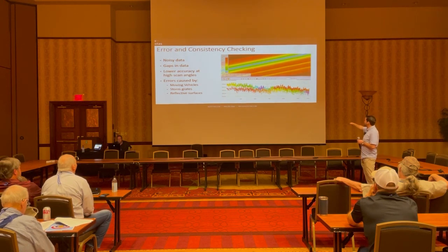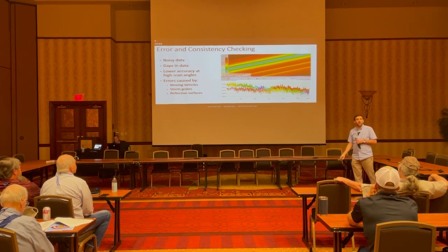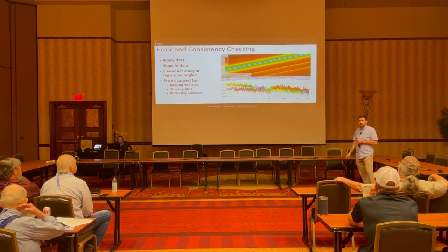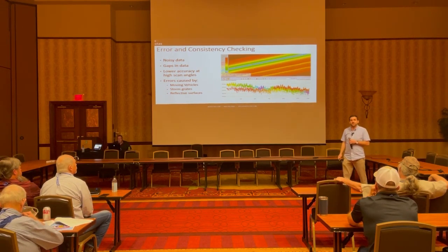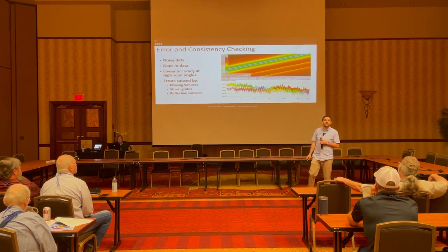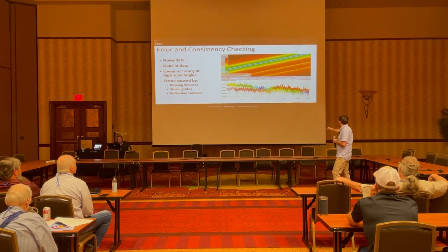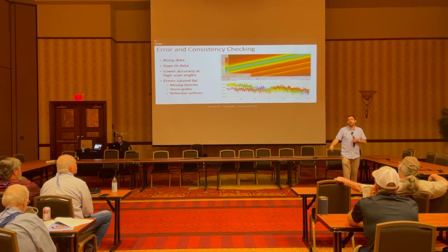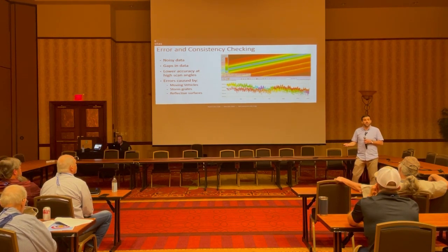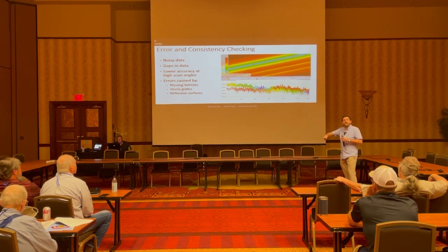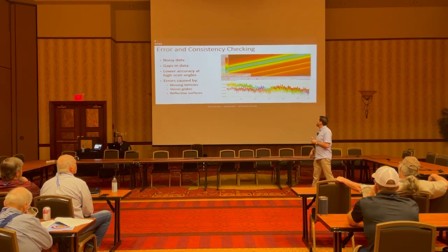This rainbow mess of colors actually means something to someone that does a lot of LiDAR data processing, where the colorization is by the LiDAR scan angle, and at high scan angles, you're seeing significantly higher deviation from the mean. So that's these red lines. The further you get away from the center underneath the drone, on some applications, if your LiDAR unit isn't calibrated, that can create error. There are different ways of checking for error in that error checking step.